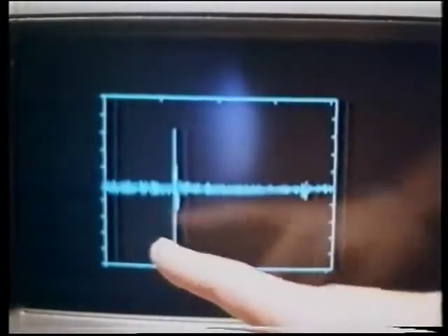You can see that it's rather noisy around the 0 volts level. And this is basically because a narrow pulse doesn't enable us to get much energy into the speaker. But we can get over that problem by averaging lots of impulses together. Let me show you.